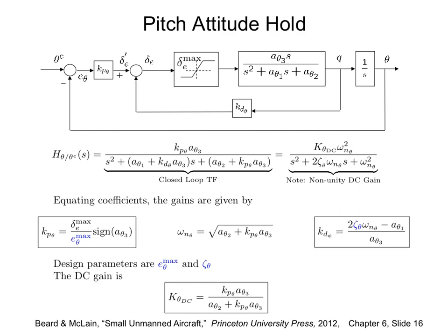Okay, so our first PID loop for the longitudinal is the pitch attitude hold. The idea is to compute your elevator, right? I keep saying aileron, but aileron was to control roll. So we are trying to choose the elevator angle to give you a particular desired pitch angle, the commanded pitch angle, right? So this is the closed loop transfer function we have.